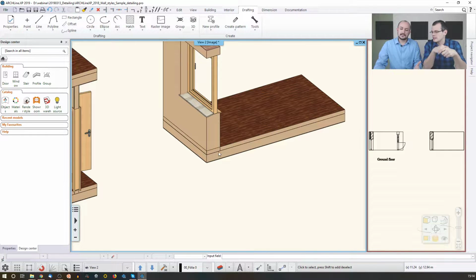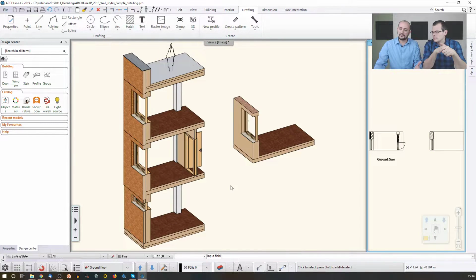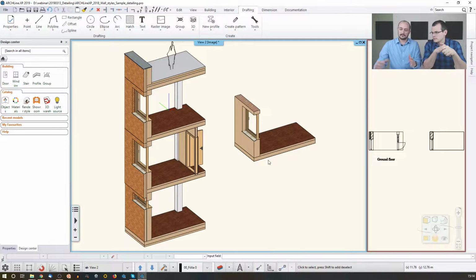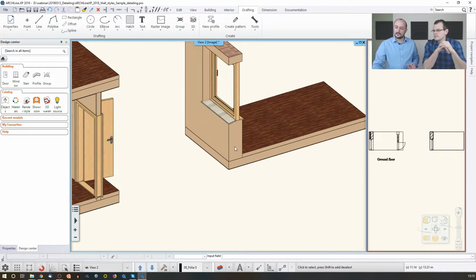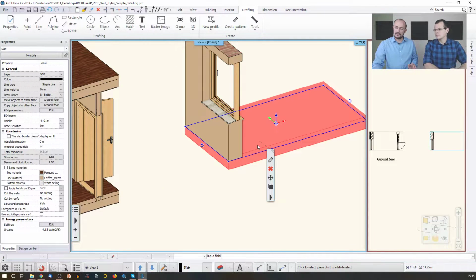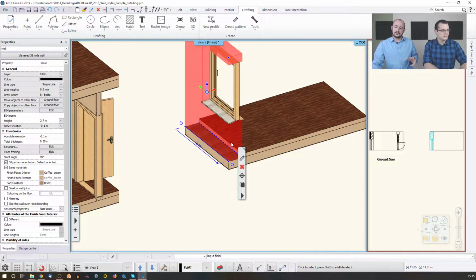Well, this is only a matter of rebuilding the 3D. When I rebuild the 3D, the connections become correct. They were just overlapping temporarily. But now they are occupying their own space, and they are proper, and the layer is where it should be. So this way you can set up the starting point of the level, either just literally typing the value or bounding it to a value of the level.